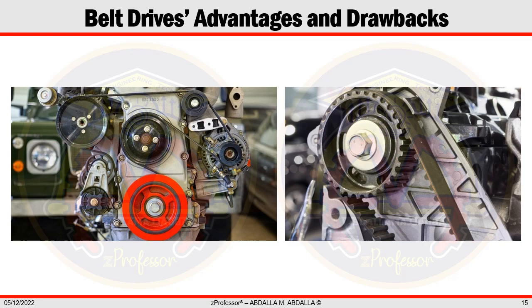The inherent elastic creep between the belt and the pulleys, except for timing belts, causes the speed ratio of a belt drive to be inaccurate. Belt life may also be shortened by belt slippage. In addition, the coefficient of friction and interfacial pressure between the belt and the pulleys limits the transmission of power and torque. A belt must be installed on pulleys with the correct initial tension in order to assure effective operation, and belt tensioning mechanisms are necessary to keep the initial tension in belt drive.